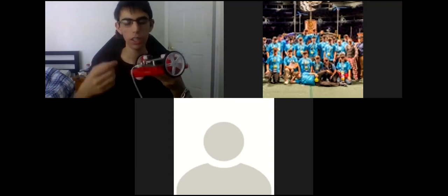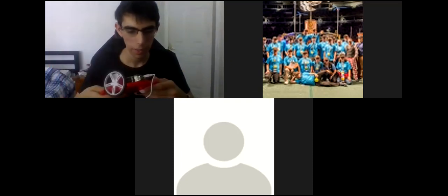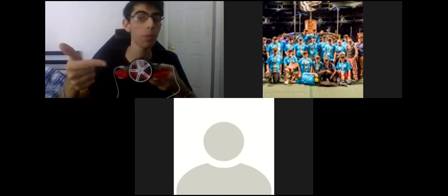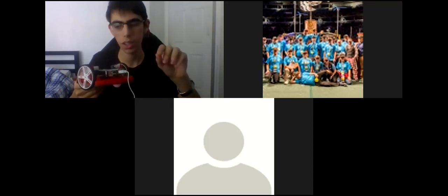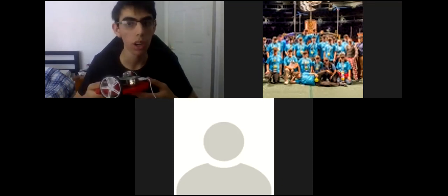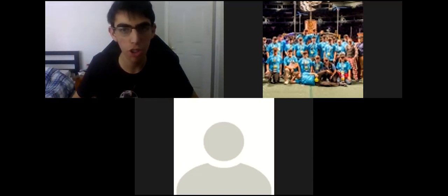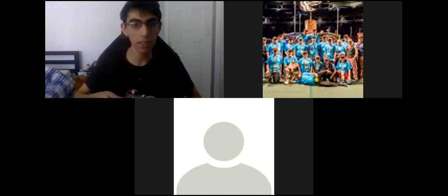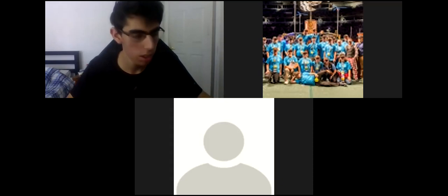You do that, then you turn on the robot while connected with the Wi-Fi or the Ethernet cable, and you're gonna go to the website. On the website, you're gonna find a button that says update firmware. You're gonna click that one, and it's gonna do a long process. After it's done, you're ready to program the robot. So that is a very short, fast explanation of what we are gonna do next time.